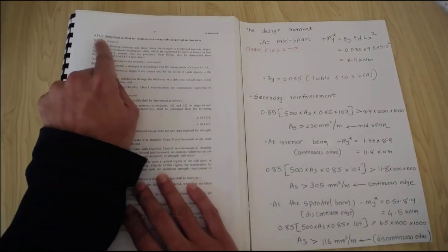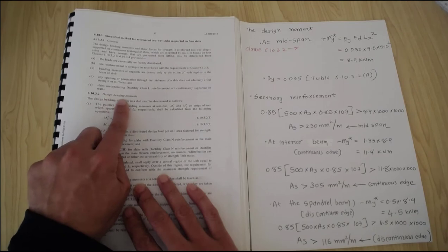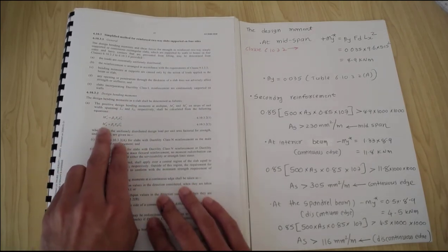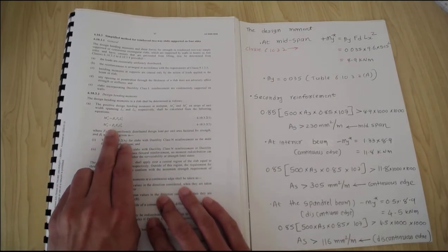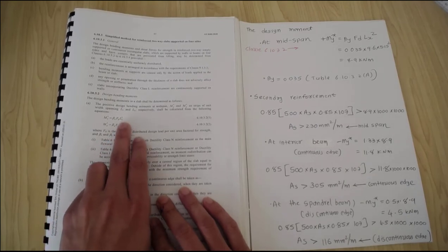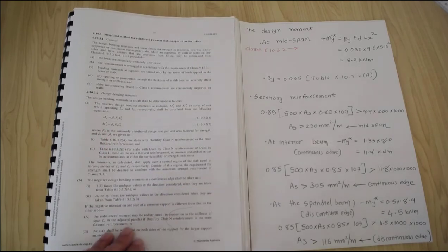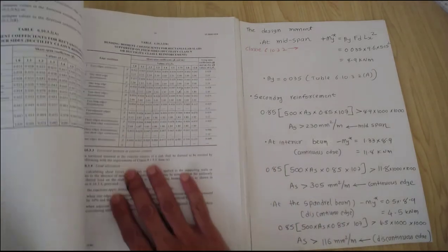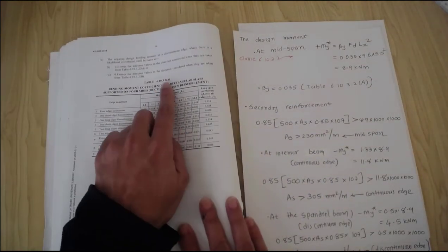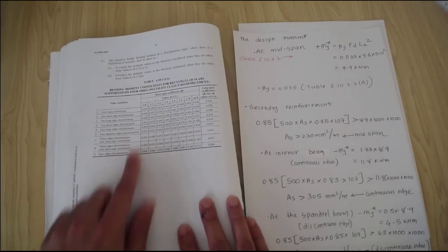That clause is clause 6.10.3, which is structural analysis, where you have the design bending moments. In here we have my, which is beta y fd lx squared. Please note we always multiply with lx regardless, the only difference is your beta y. How can you find that beta y? If you turn the page over, there is a table 6.10.3.2a, where you have two adjacent edges discontinuous.